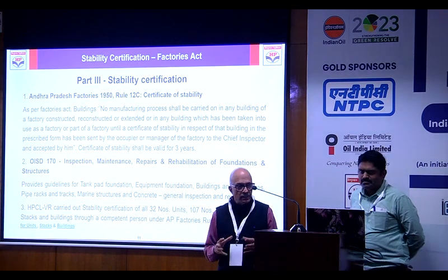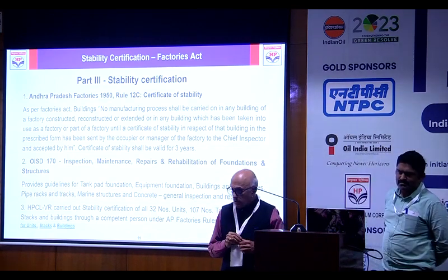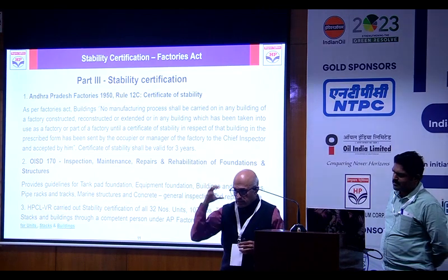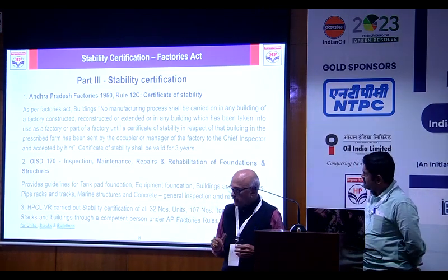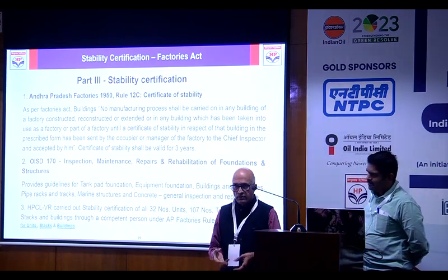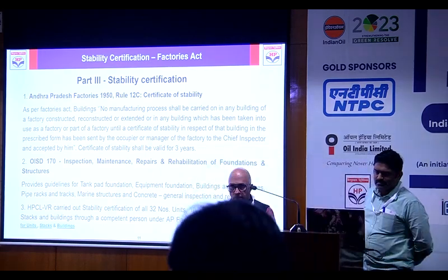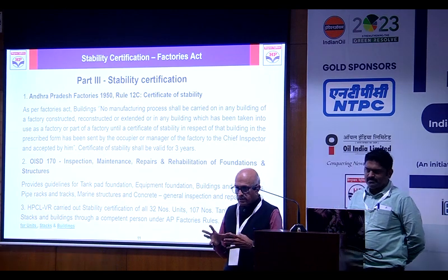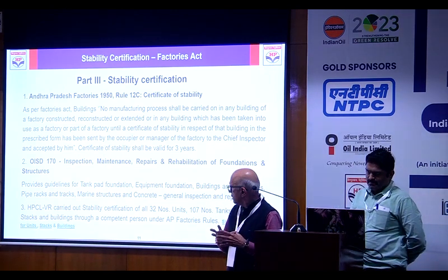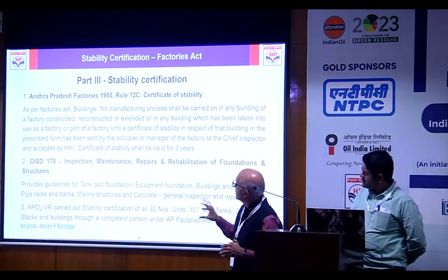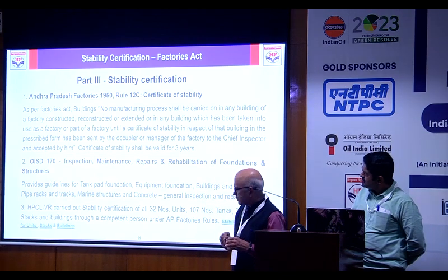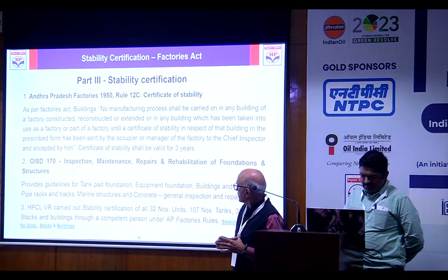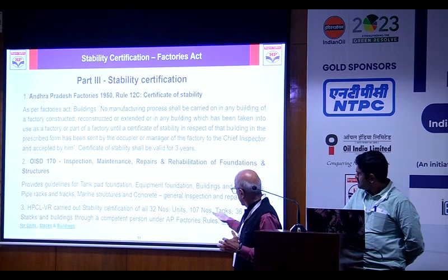Why this is brought up here is that somebody also mentioned it elsewhere. The support is as important as the equipment that is sitting on it or the pipeline that is sitting on the support. Particularly in a fire damage case, if the support gives way, the entire equipment will collapse. So it is very important that the foundation is correct and fireproofing is exact. That is a very important element in asset integrity. So using these things, we carried out all of this.